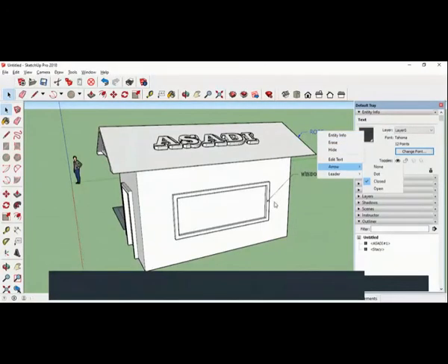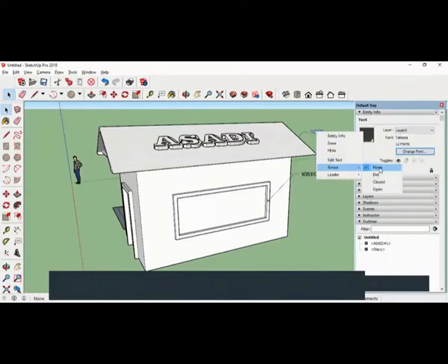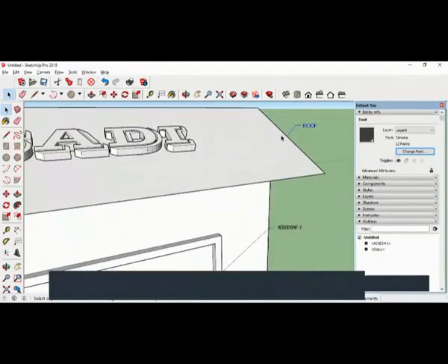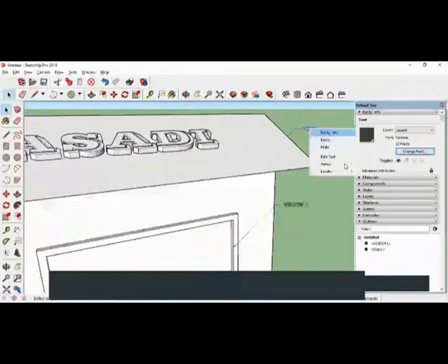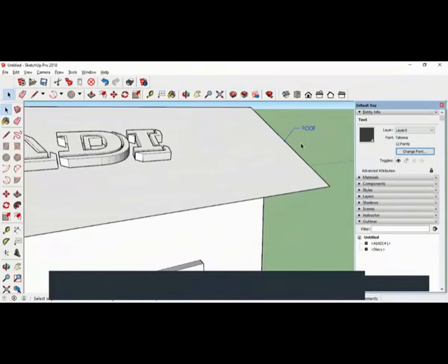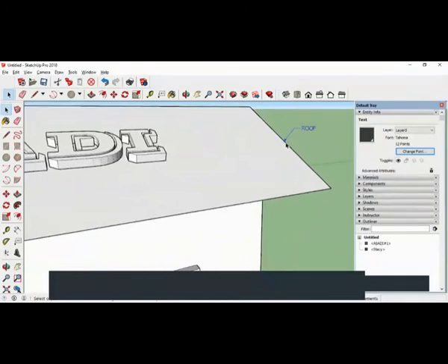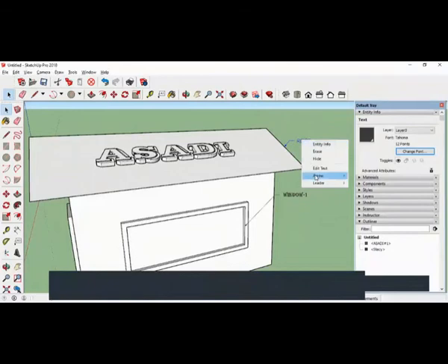You can change the arrow. Now there is an arrow coming here. There are 3 types of arrows. If you don't want an arrow, there is no arrow here. Arrow has gone. Only the line is there. Right click, arrow, dot. So you are selecting with a dot. Very small dot is there. Right click, arrow, closed. You get a closed arrow. Right click, arrow, open. Get an open. You can do a lot of things. Just select it, right click, and you can do.